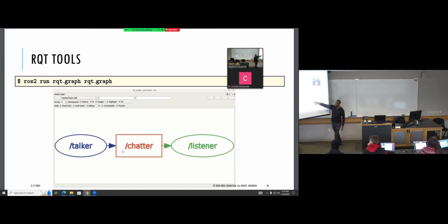And this could actually even be on different networks. So this could be your robot posting your LiDAR data, and I have my laptop listen to that. In ROS1, you have a little bit of an extra thing it connects to, but they can still find each other, and you can share information through that. You just need to have the same last subnet. So once you get your IP set up, with a wireless router or something you can all connect to, it might be easier, and you can share messages.